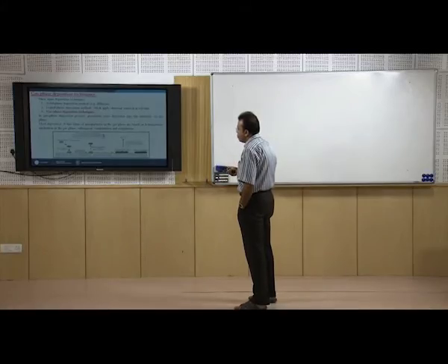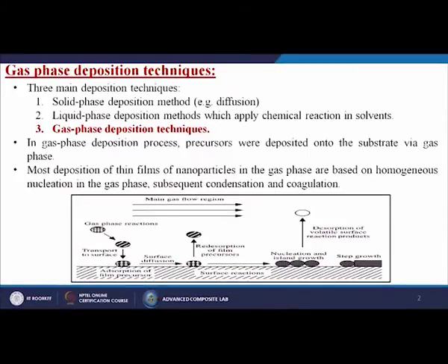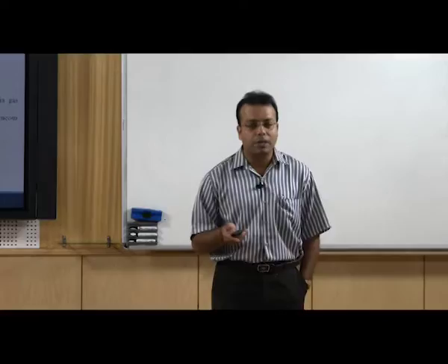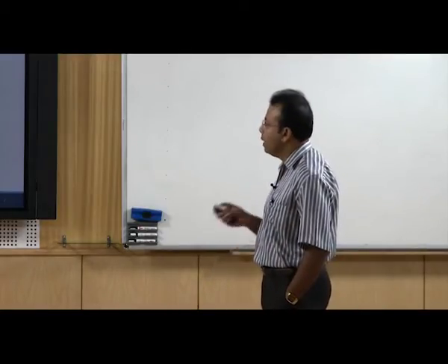From this case we can understand that we have a thin film and we are flowing the gas on top of it. From the gas phase the molecules come, and first the adsorption of the film precursor takes place onto the surface. Then some volatile gas is removed from the substrate, and the pure molecules attach to the surface and react. Then nucleation and growth take place, and some volatile or toxic gas comes out from the material surface. By this layer-by-layer step growth mechanism, the film deposition takes place.